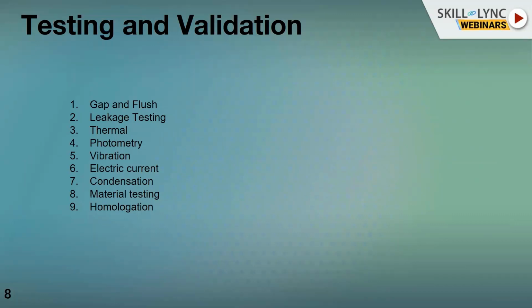There is a software of ANSYS. You can check into that, and this will also help you to identify your gap and flush requirement, because in the vibration you can check your mounting points. You have to provide the mounting point as an input, and then it will tell you after the vibration how much warpage is coming. So that will also help you to identify the gap and flush requirement.